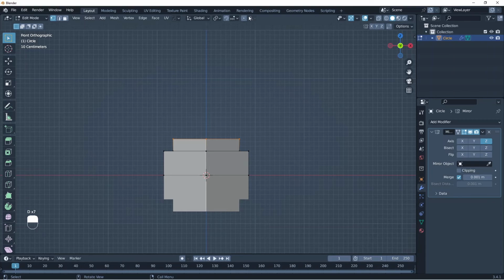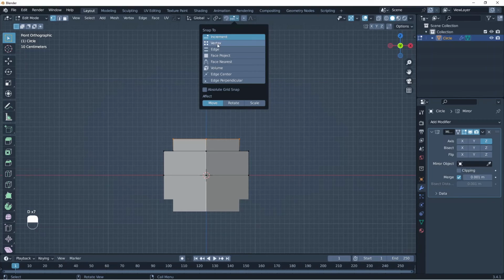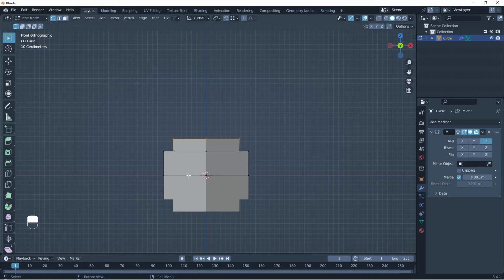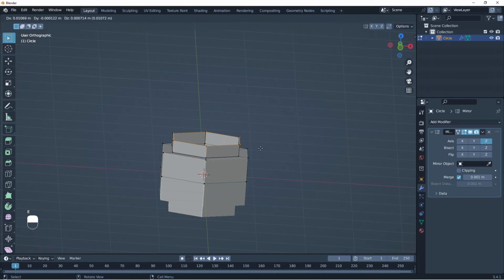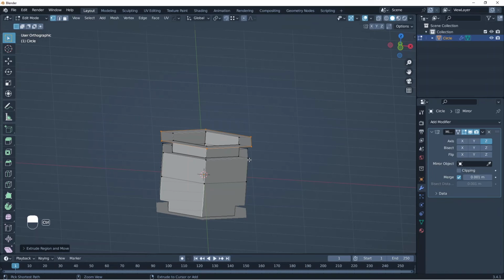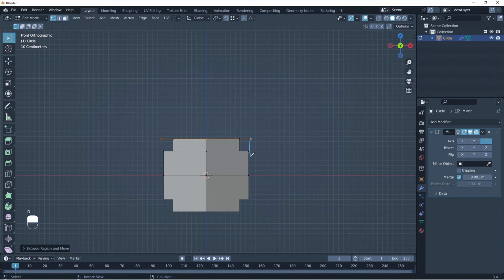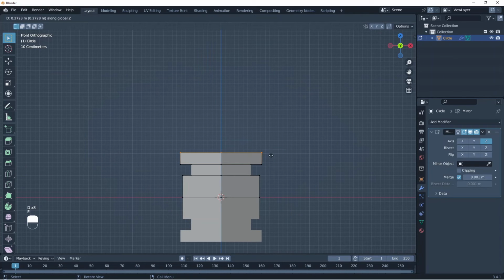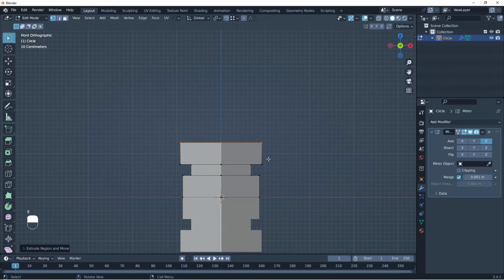So we're just going to activate our snap tool on the vertex and on the scale. I'm going to press E and S for the scale, and if I press Ctrl, see, it's going to snap whenever I go into this vertex right here. That means it's on the exact same position. And I'm going to extrude it again on Z, again 0.5.